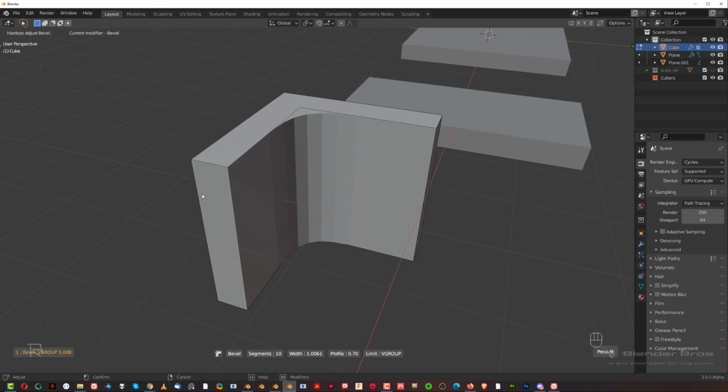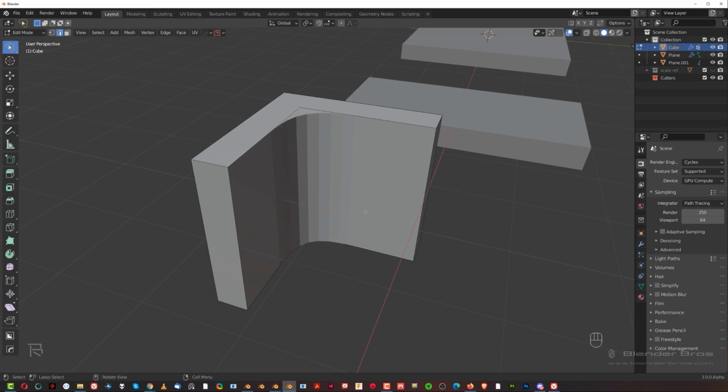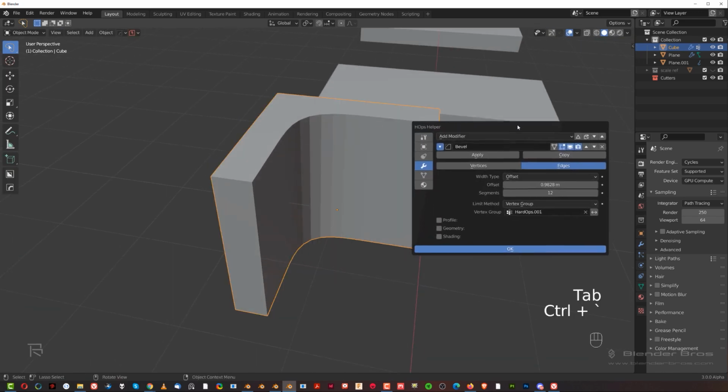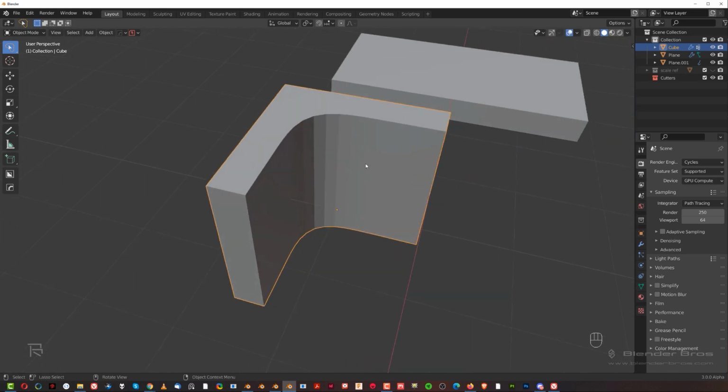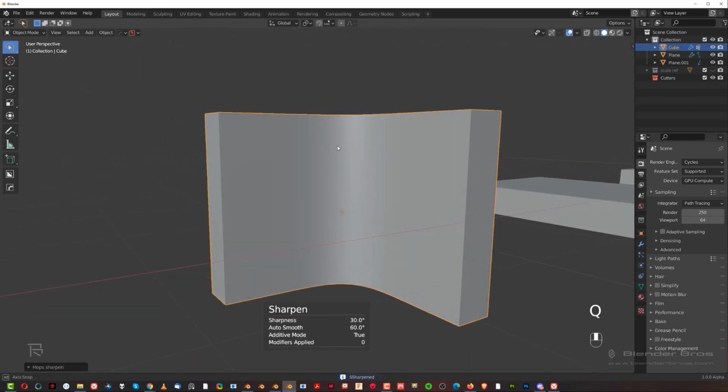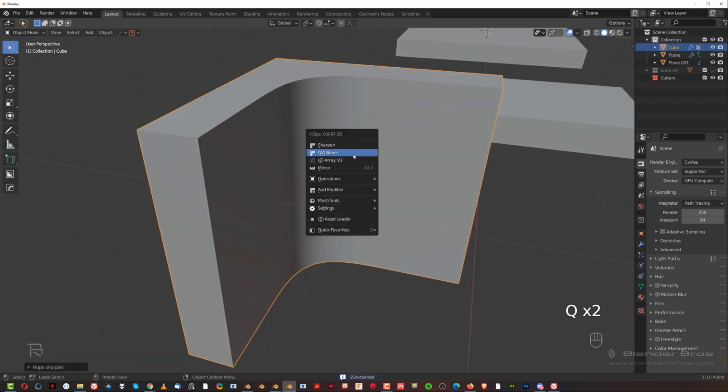Or you can actually make, yeah, 10 is enough. I think maybe 12 would be better, but make sure it's even. Now the reason why it has to be even is because it will allow you to change the resolution later on if you need to. Now for the smoothness of the width of the curve, I think we're going to go with an exact number here. So let's go to the bevel and change this to 1. Okay, so offset is going to be 1, so it's going to be identical on all of them, and click this and sharpen to smooth it.